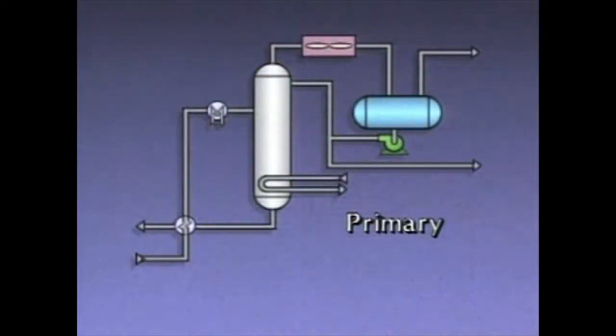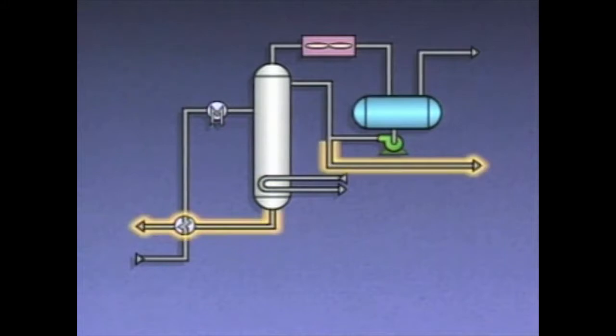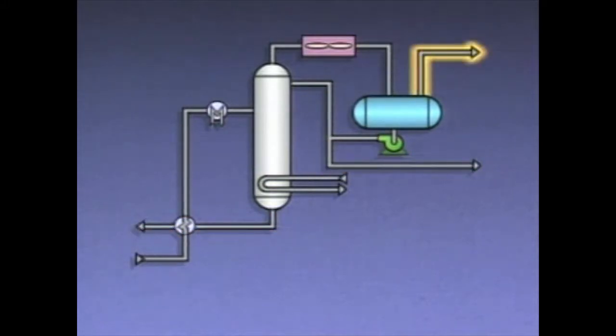Primary energy flows are associated with heat transfer into or out of the system. For example, the heat input to the reboiler and feed preheater, and the heat that is transferred as overhead vapor in the condenser. Most of the heat input to the tower from the reboiler and the feed preheater is removed by the condenser. Heat also leaves the tower in the products, in the gases that are removed from the system, and by heat transfer through equipment casing and piping.